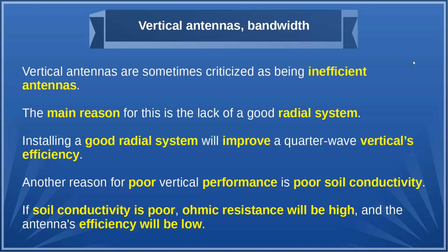If it's rained recently, you have maybe a better ground plane effect. And then as time goes on without rain, it seems like your SWR probably would change a little bit because it's not as efficient. Well, here in Merritt Island, the water table is like 5 or 6 feet down, and it's becoming more saltwater, which is good for this purpose.